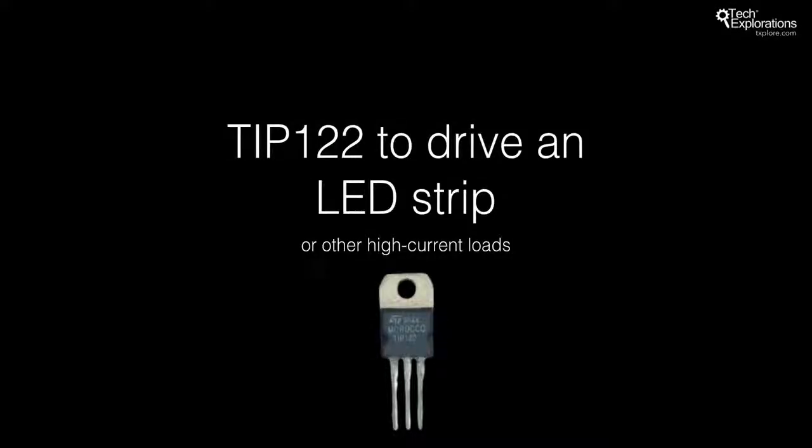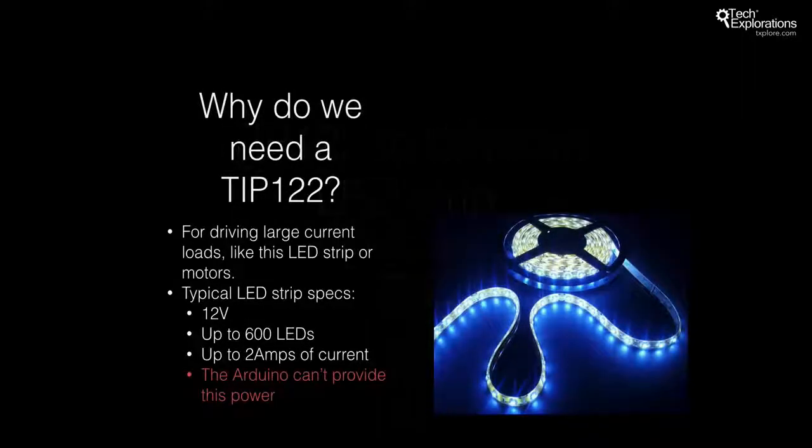Hi and welcome back. In this lecture, I'm going to show you how to use a TIP122 Darlington transistor to drive an LED strip. You could use the same technique to drive other high current loads like motors, for example. So why do we need a TIP122? Well, we need it to drive large current loads. For example, this LED strip here or motors.